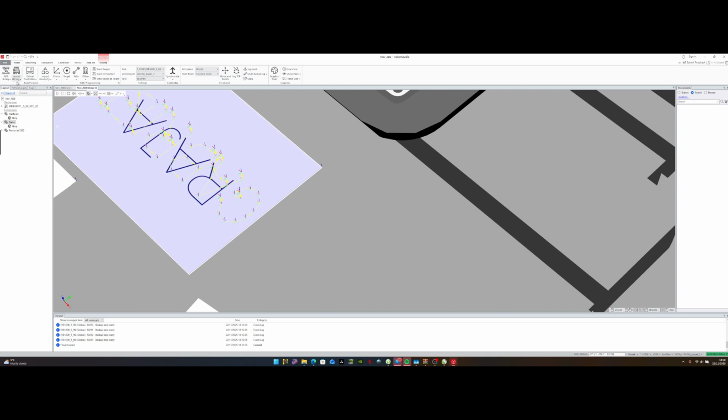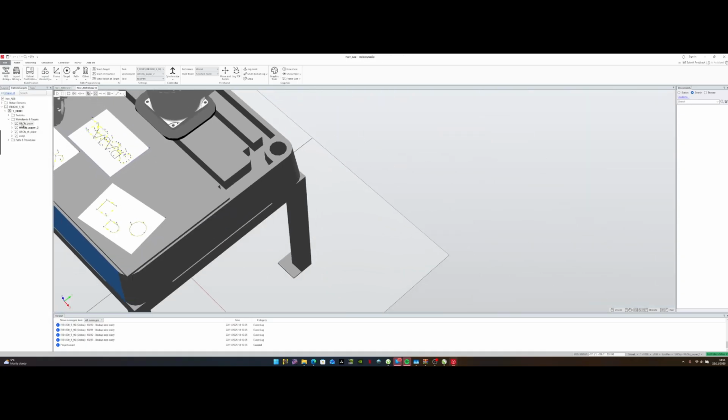Go back to home, go to paths and targets. Okay, we're going to select the station. Go to work objects and targets. Under work object and targets, we're going to select work object paper. These are all the targets that concern work object paper 2. Very important. By the way, if you notice, there are 4 work objects here. This table, where is it? Yeah.